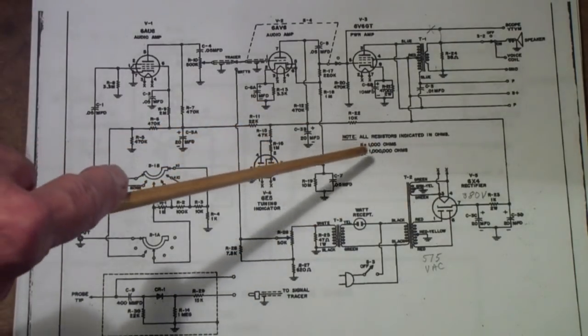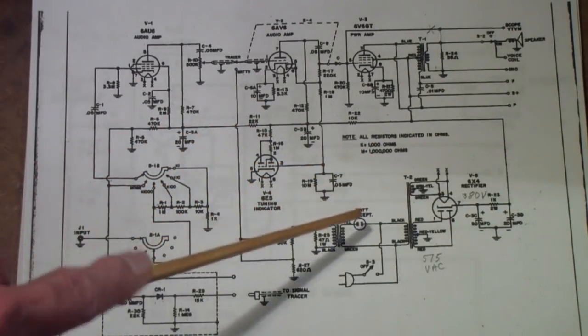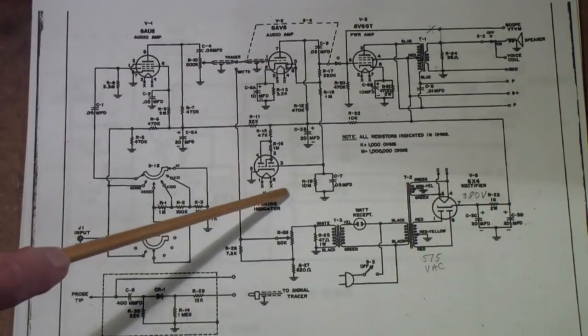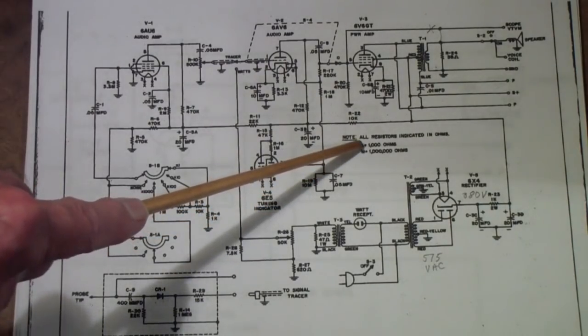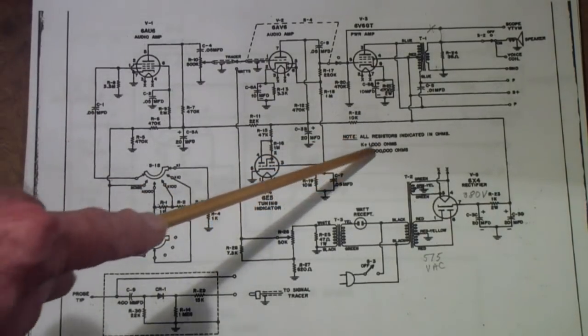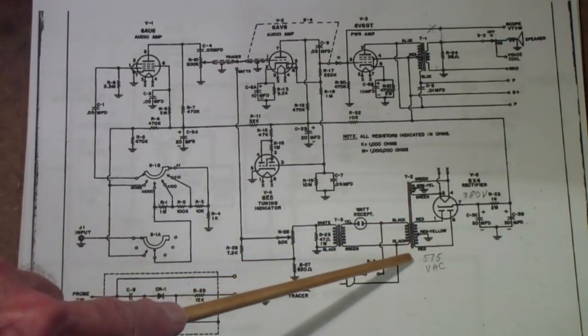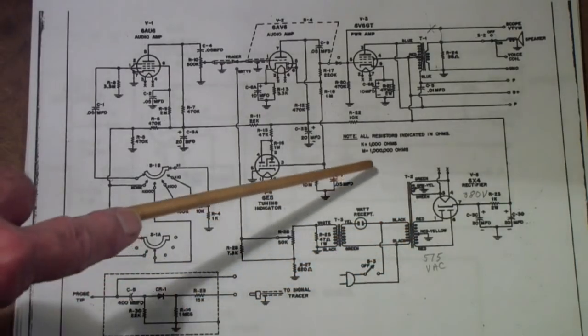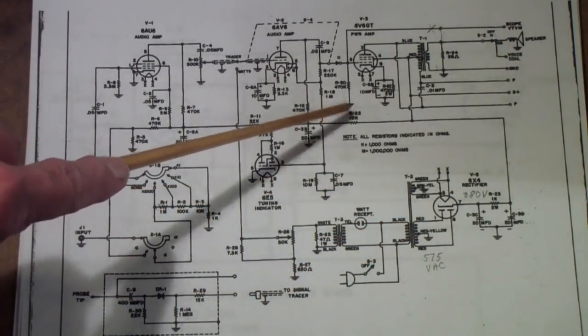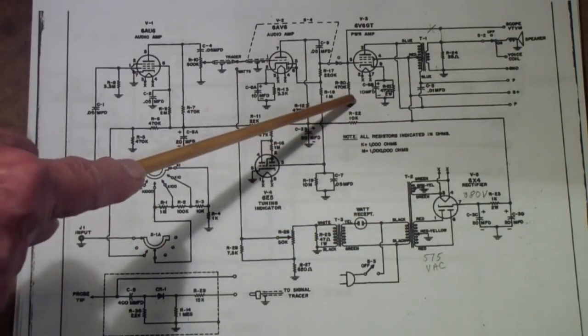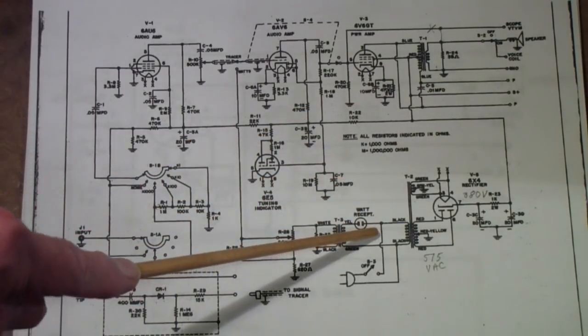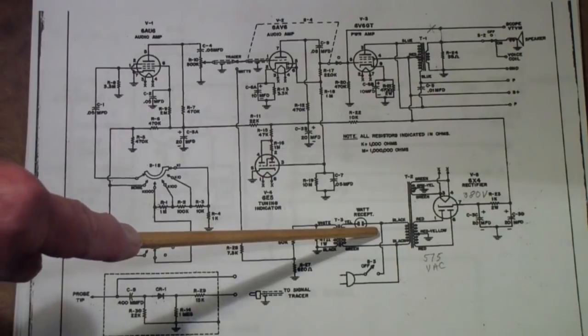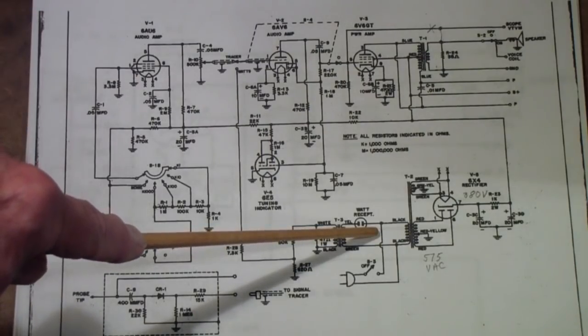We'll use zero crossing detectors to synchronize. We'll have a ramp generator that generates a nice linear ramp at 275 volts, and then we will switch it from one tube to the other tube using these MOSFETs and so on, and you've already spent a couple thousand dollars.